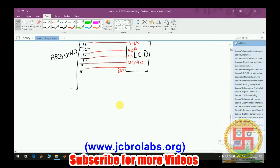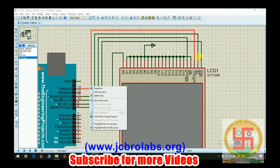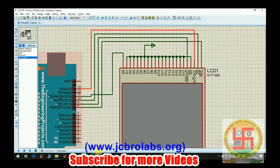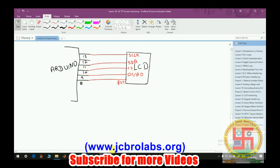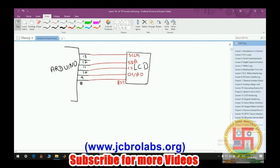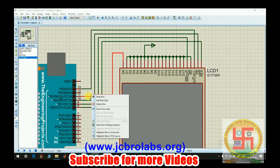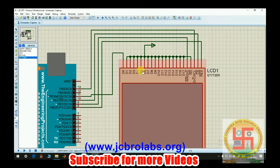Similarly, we have this SCL, which is connected to pin number 13. Then we have the chip select pin, which is connected to pin number 10. Then we have the RES pin, which is connected to pin number 8 as we talked about. Here this is the SDA line, connected to D0 of this LCD. And the rest of the pins are connected to plus VCC.